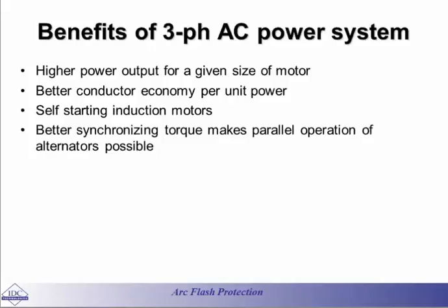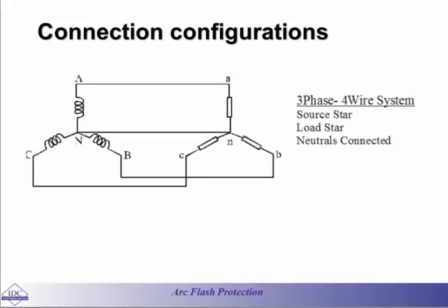That's a fact. Therefore, if we are running three-phase motors in terms of delivering power, it would be superior to having single-phase motors. In terms of the economy, cost-effectiveness, in terms of using, for example, the conductors, yes, that would be much better. In terms of the starting of the motors, yes, that would be better to have three-phase. In terms of, for example, synchronizing the torque between the mechanical parts of a machine, especially when you are running them in parallel, it would be much better.